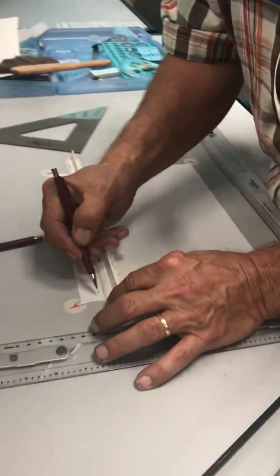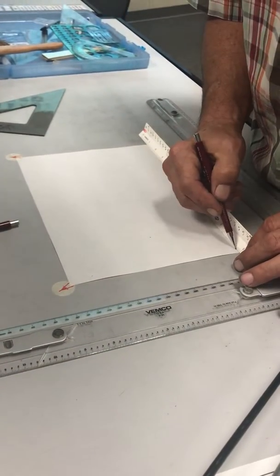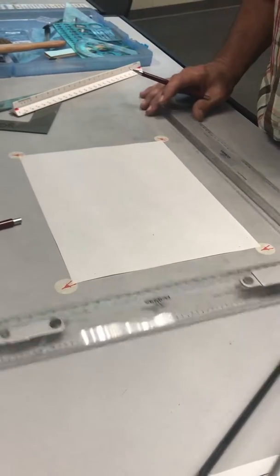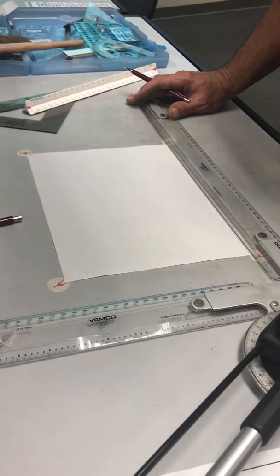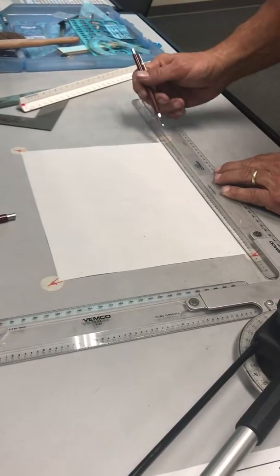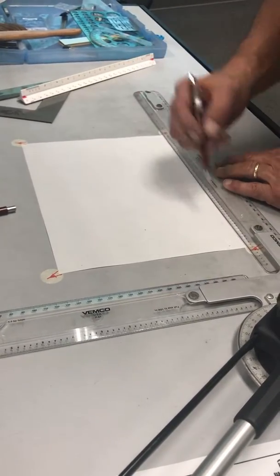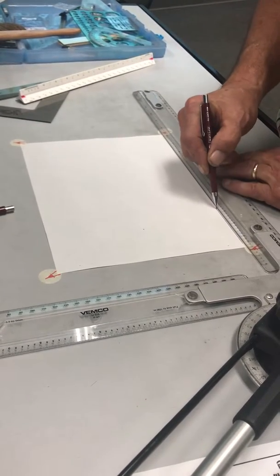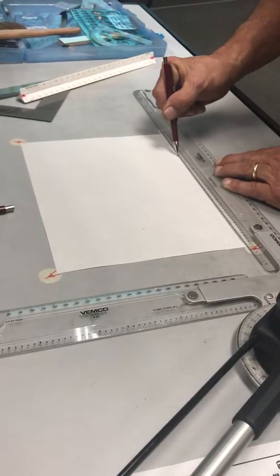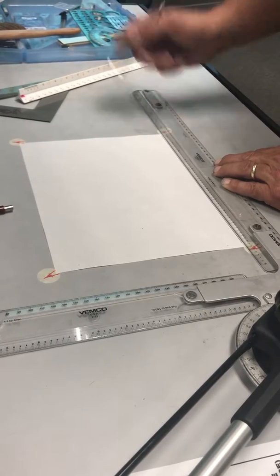I'm going to go ahead and do my verticals. So I'm going to come off the edge of the paper, mark a 1/4 here, mark a 1/4 here. Now, I'm going to take my drafting machine and I'm going to draw a straight line. Now, you don't push your pencil. You always pull. You always want to pull when you draw your lines. All right, so I'm going to start about right here, and now as I pull, I'm also rotating my pencil, okay?